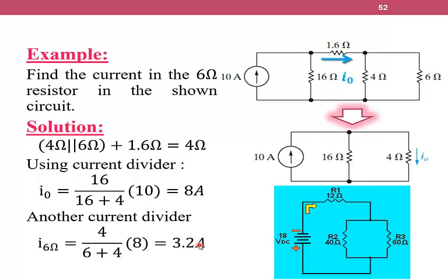But if you would like to benefit from the analytical solution, you may verify your answer. If you made the circuit experimentally and you would like to verify whether your answer is correct or not, you may use one of the methods that we have explained in this video, like KVL, KCL, voltage divider, and current divider, and you may use, of course, Ohm's law.